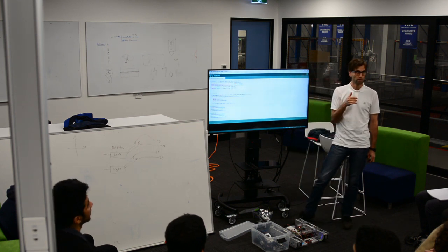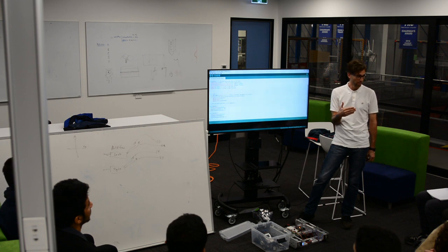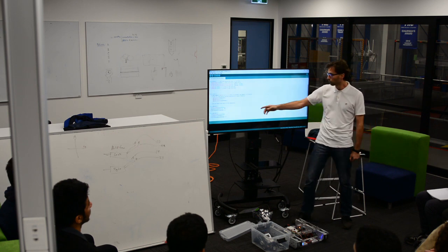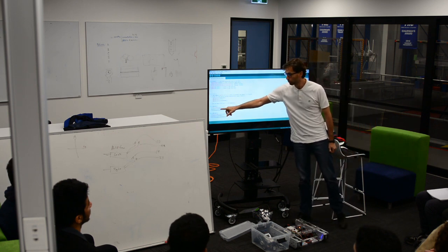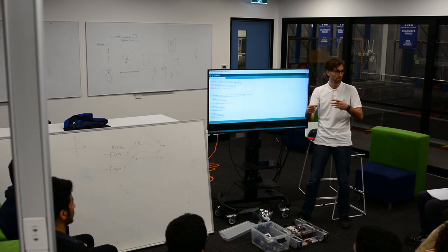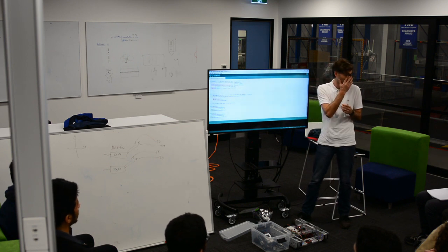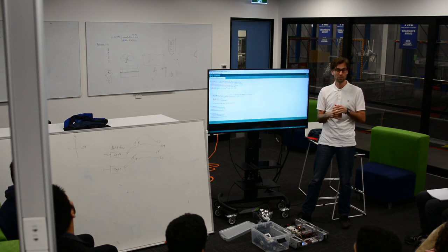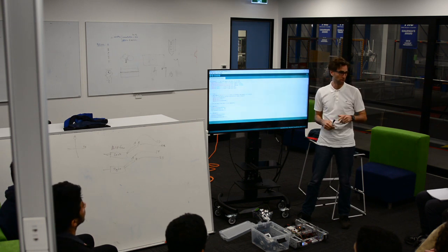So if you have a high priority event, what you don't want that event to be is long and tedious, right? Because it happens a lot, and it takes priority over everything else. So if you, for example, put in here a serial print or some communication protocol where you're going to send a bunch of bits back and forth to the computer over the USB, that's a disaster because it's going to mean that the whole process slows way down.